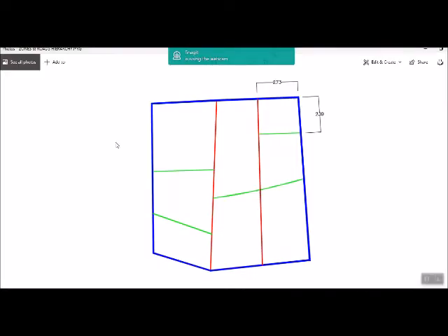Our goal is to calculate 2 main things in this video. The first thing is the Skim matrix, or the time matrix, which is the free flow time, the free traveling time between each zone and another. The free traveling time is the time that you take to move from one zone to another zone when the network is all empty.